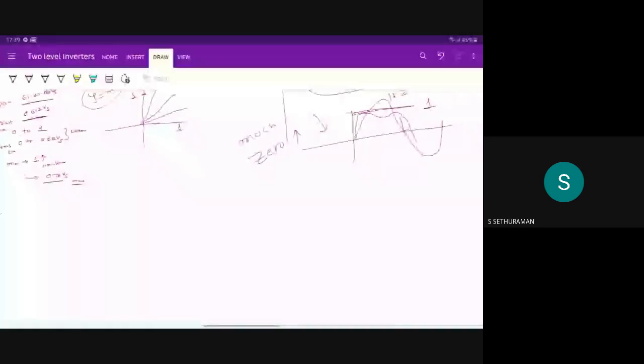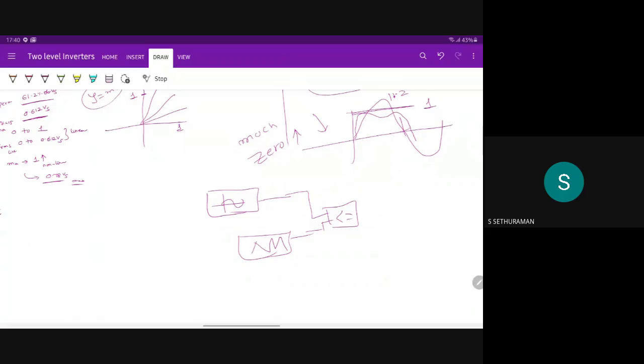See here how normally we do PWM. In simulation you have this sine wave, and you will generate this carrier. This is a triangle carrier. You need to compare these two. This will generate switch S1 and the inverted one will generate switch S4. That's it. This is how normally we generate a sine PWM.